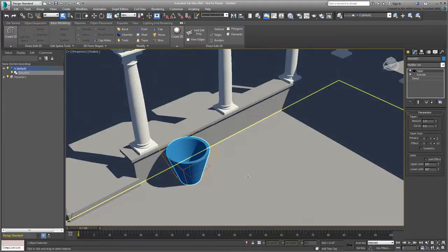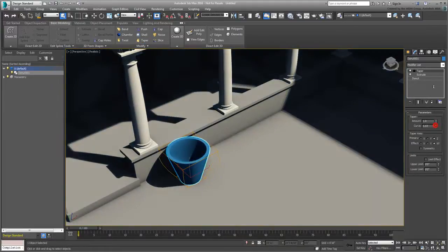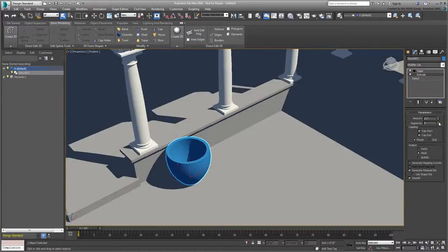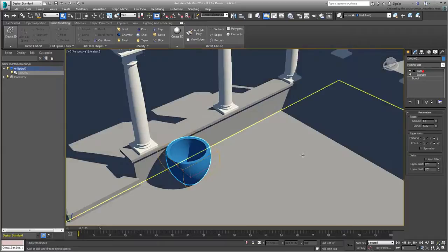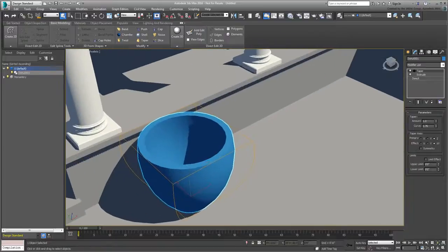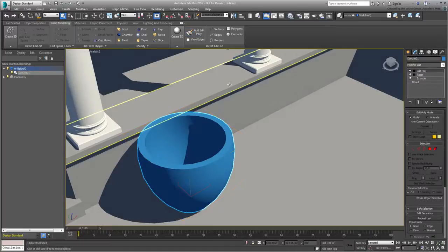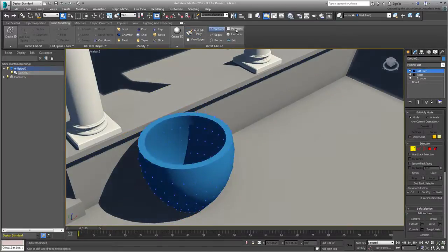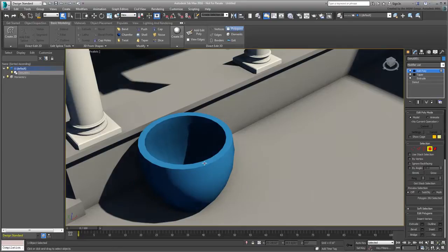Perhaps adding a taper modifier would create a nice effect. In order to edit those parameters, you still do that in the Modify panel, but the general shape and form was set from the same UI. You can even do some basic poly modeling just using the design ribbon. This is done by adding an Edit Poly modifier directly from the ribbon, and sub-object selection can also be accessed directly from that interface. To actually make changes, such as extruding or beveling polygons for example, you still rely on the Modify panel or the Quad menu.